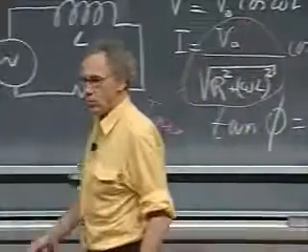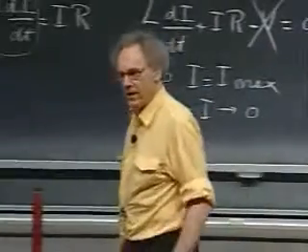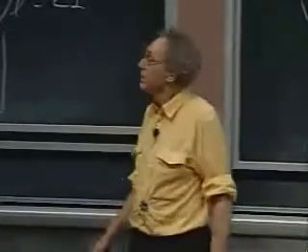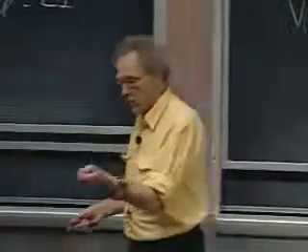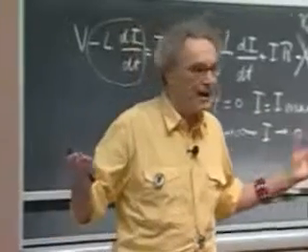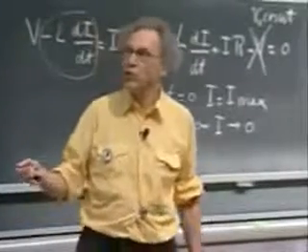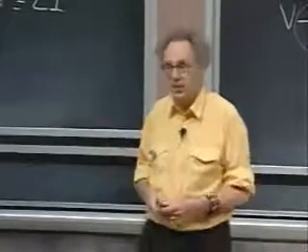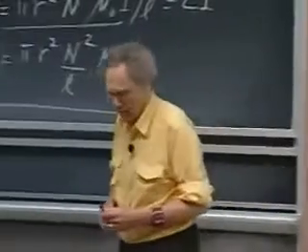I'm going to make you listen to music. And there will be violins which produce probably 3,000, 4,000, 5,000 hertz. And then I will turn on all of a sudden the 10 millihenry. So first I will make you listen to music whereby there is no 10 millihenry in there. And then I will turn on the 10 millihenry, and what you will hear is that the violins disappear. Because the current reduction is now huge on the high frequency, but is very little on the low frequency. And that's the idea of what a self-inductor can do for you.